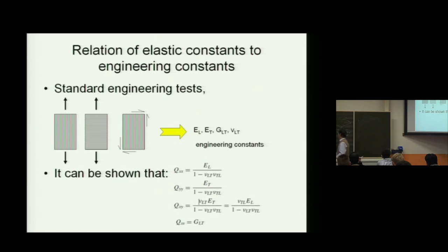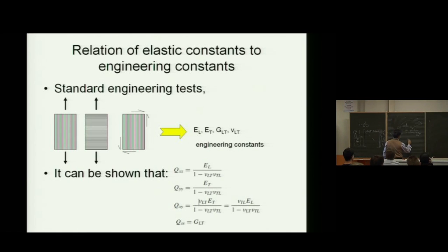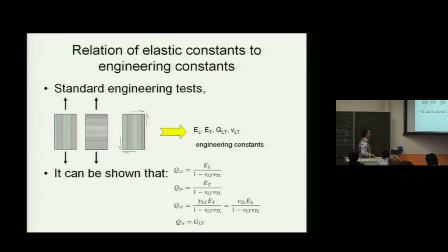So in general, my Poisson's ratio from this test is minus epsilon y over epsilon x. The transverse strain epsilon y is in this direction perpendicular to the loading for this specimen. Longitudinal strain is along the load. The ratio of the two, with a minus sign because one of them is compressive, so I can get a positive value, is my Poisson's ratio.